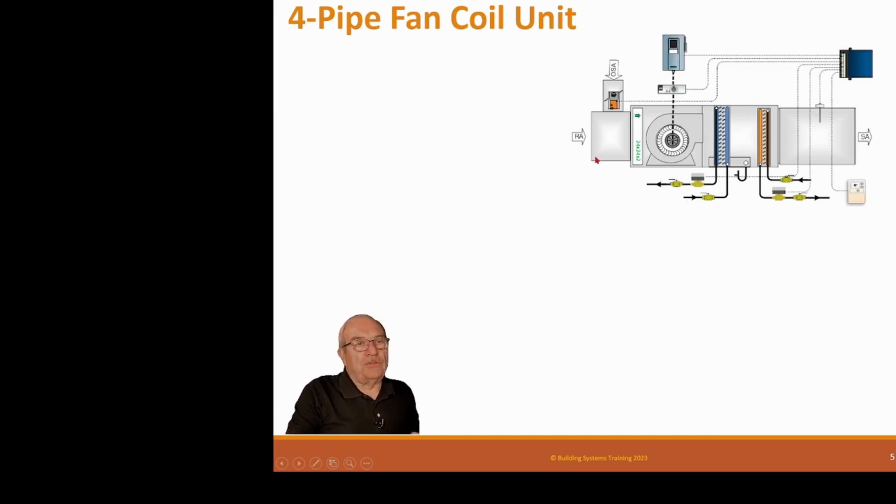So then the control system on this one would be similar to the others. Again, it's constant volume, so the fan is start-stop to the starter, and has a current switch for status. We have an outside air damper again, the same thing as the other unit, but it's balanced. When it's open, it's at the right airflow for outside air, and when it's off, it's off. And then we have a chill water valve, and then we have a hot water valve.